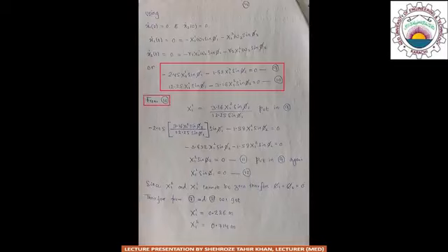we can find the value of the mode shape x11 in terms of the mode shape x21 and phase angles phi1 and phi2, and this value of mode shape x11 is substituted in equation 9 so that equation 11 is yielded as follows: x21 sine phi2 is equal to 0.